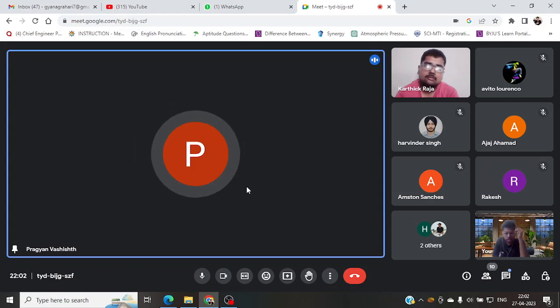So now let me get to the working. We have the following three components: an electromagnet to produce magnetic flux; second, the test subject on which we have to do the testing; and third, the magnetic particles. So here, we sprinkle the magnetic particles all over the test subject.